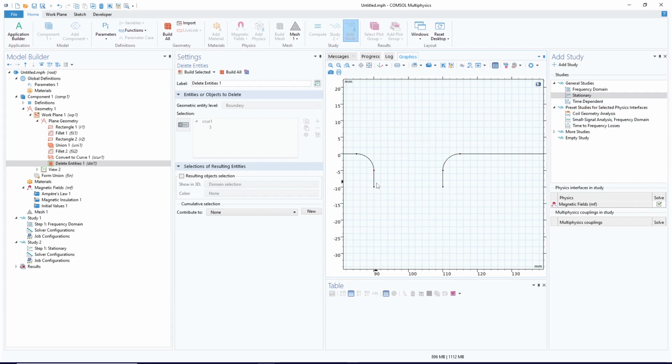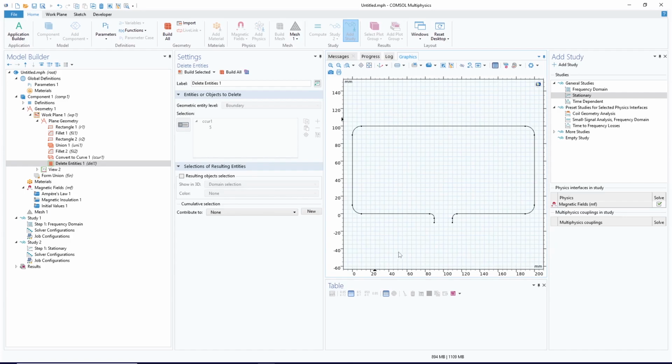Now, if you want to analyze the inductance in 3D, we need to define a coil, and for this coil we should say where the current enters and where the current goes out. Those boundaries where the current goes in and where the current goes out of the coil have to face an external boundary. Because we are going to put air around this coil, that area will not be an external boundary, it will be internal boundaries.